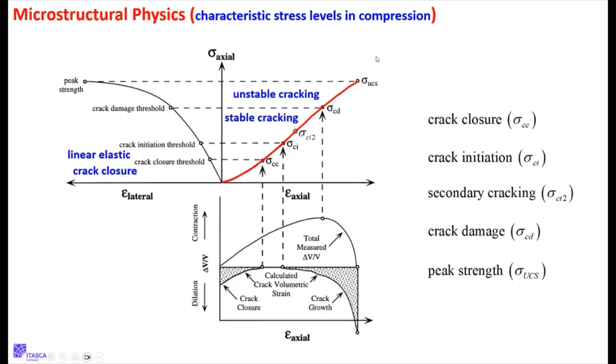And so this is what we call the UCS, right? The typical rock mechanics test has all this complicated stuff going on, and we get one number out of it. We get two numbers out of it. We measure this initial slope in this linear region, and we get the slope of this curve. We call it Young's modulus. We call the other one Poisson ratio, and we get the peak, and we call that UCS. And then we say we're done, and we say we've characterized the rock.